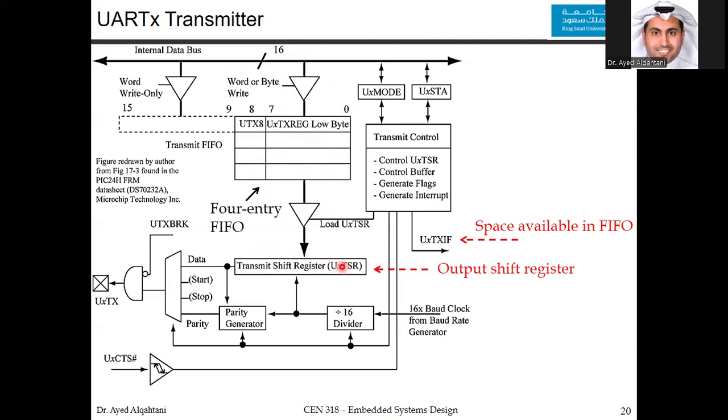Now, again, we use the same thing: we have a start bit, data bits, and then a stop bit, and so on. That's why you have this multiplexer. Remember, only data is here in the shift register, so you need to generate the start bit, followed by the data, then maybe a parity bit, and then followed by a stop bit. That's one way to send the frame.